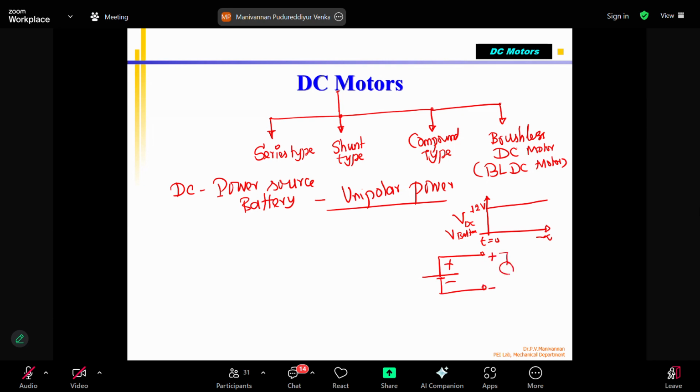If we connect a voltmeter and see the value, it will show 12 volts. For a lead acid battery used in cars, it can be 12.1, depending upon the charge level. Theoretically, we say 12 volts in fully charged condition. It can go up to 13.8 volts, the maximum voltage we will see when we talk about a battery. So the voltage remains constant with respect to the x-axis as long as I don't connect a load.